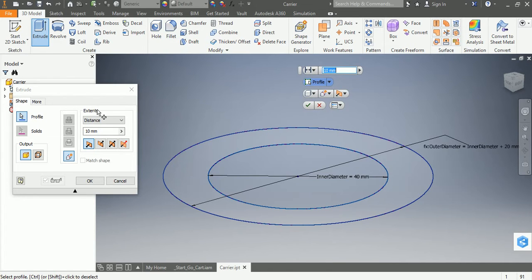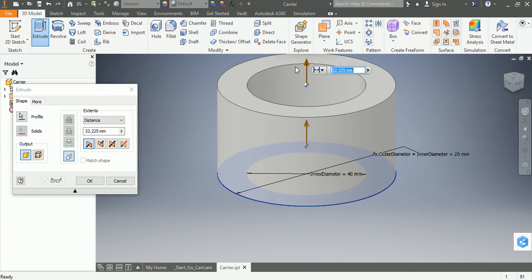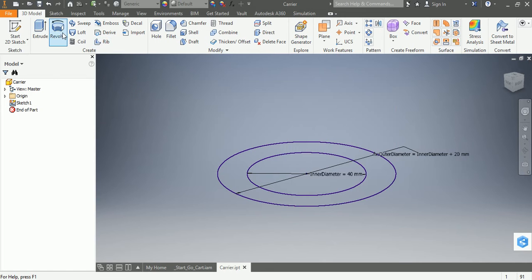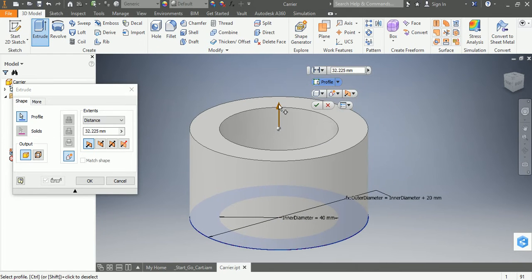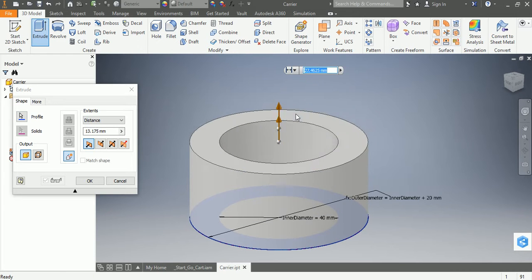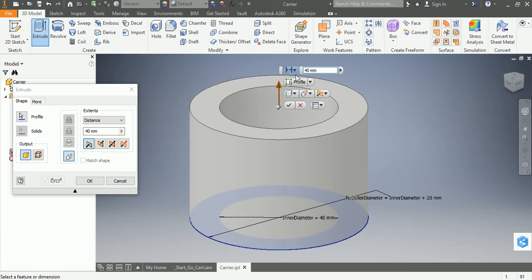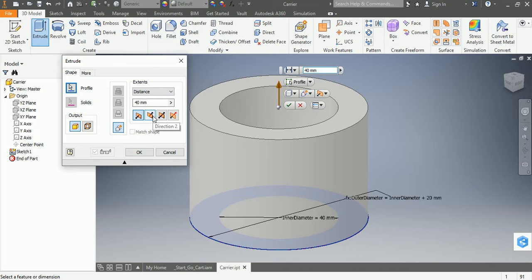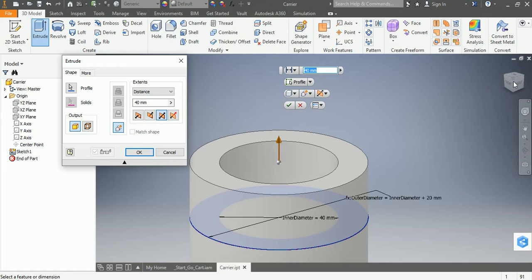It asks me to click a sketch first, and then I can drag this. I want you to play around with the settings first of all. Actually, scratch that. Now we can begin to extrude this thing. You can see extrude, and you can drag and drop. But for me, I will set an extrusion of 40. You can make the extrude on this side, or halfway.